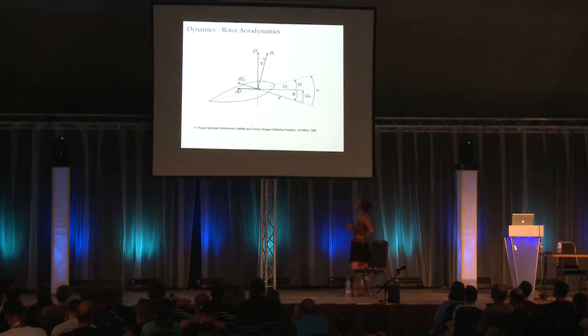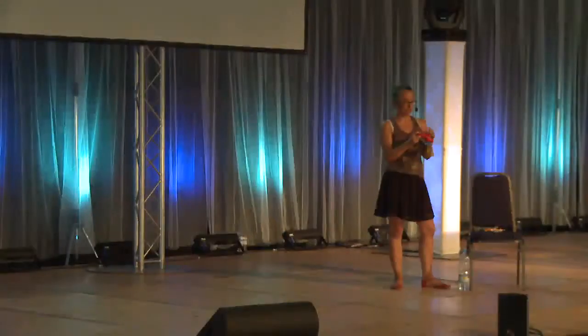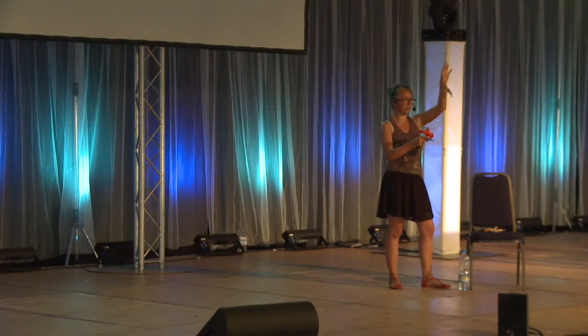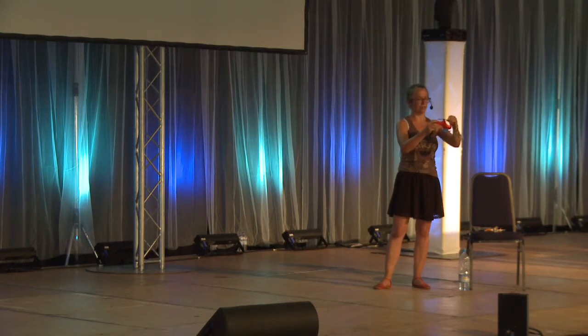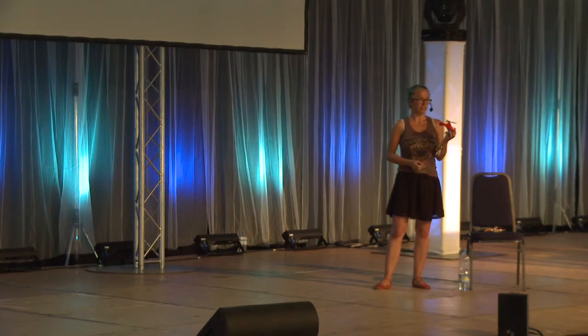There are different approaches to describe rotor aerodynamics, so what's happening when the blade is turning. One would be momentum theory. It just regards the air above here, which is basically moving at a velocity of 0, and the velocity of the air right below the blade, which is something. Then you can just compute differences and say, okay, I'm generating that and that thrust. But it does not take into account the speed of the rotor if this helicopter is pitching or something else.